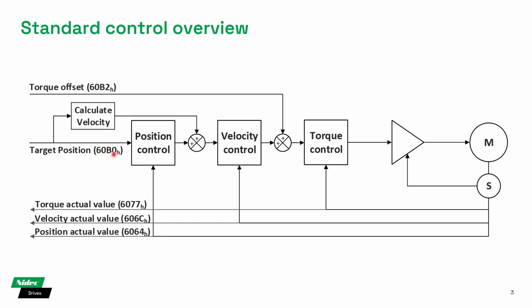Okay. Now, in normal control, if you don't do anything to an NC axis, and many other manufacturers' PLCopen type axes over EtherCAT, you'll find that the target position comes into the target, and then we go and calculate the velocity feed forward reference directly from this position, and we do that by differentiating it. So we're working out the rate of change of this position reference in order to derive the velocity, and then we feed forward that velocity into the control loops.